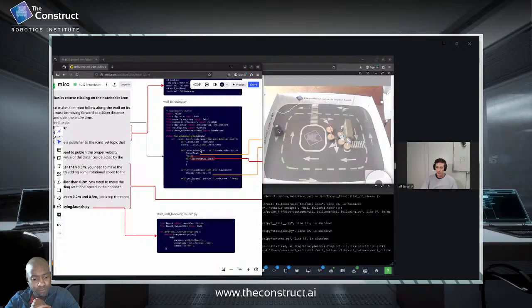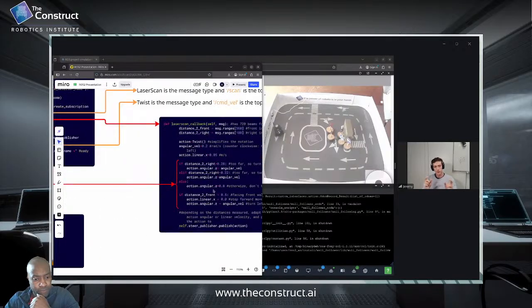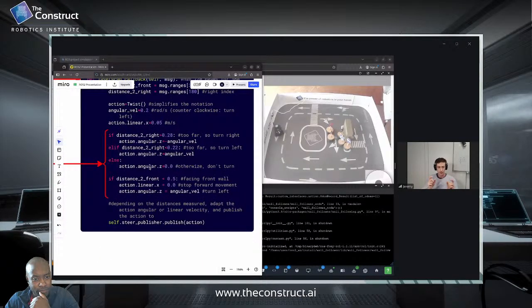I cheated a little bit with the values. Instead of 30 centimeters and 20 centimeters, I added a buffer of 2 centimeters. On my first run, I realized that since the robot has some inertia, sometimes it would go further than the distance, and if I didn't code a proper way to bring it back, it would just stop because it was out of reach of the boundaries I had set. So that was a little way for me to add some buffer.